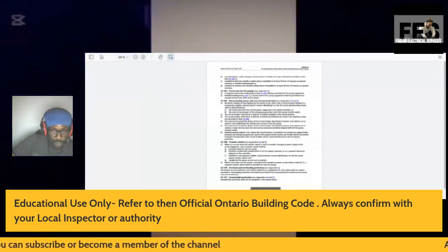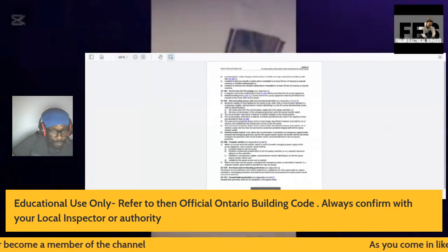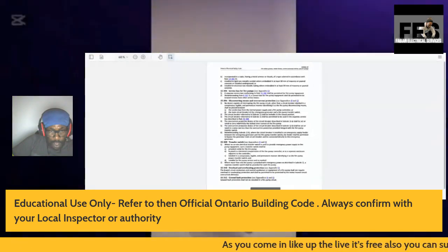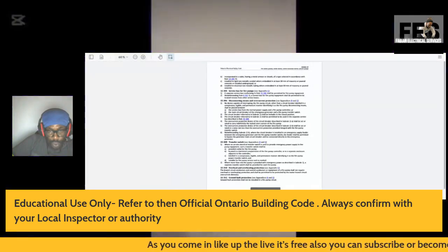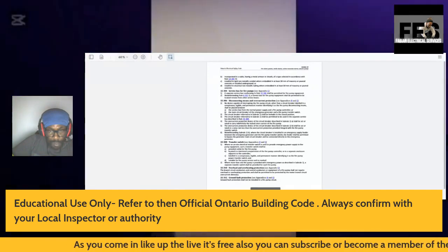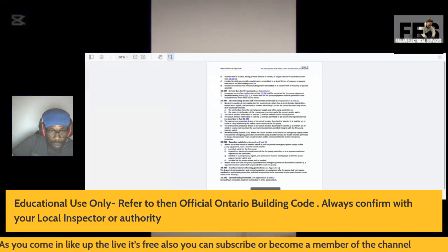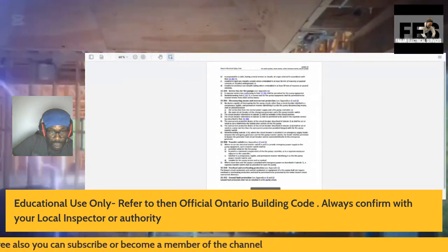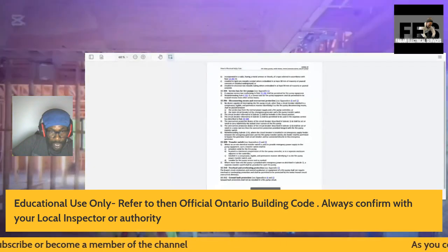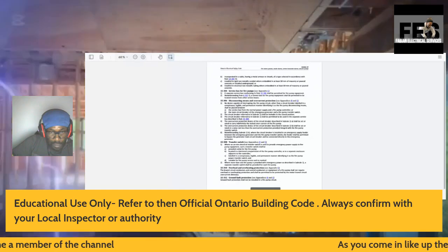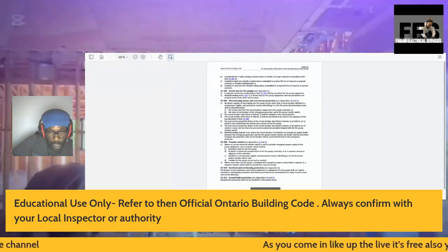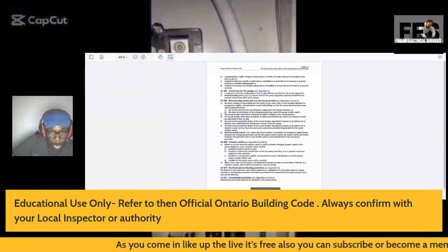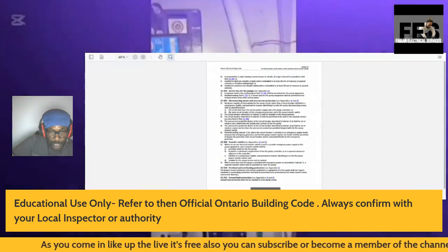It also has the transfer switch, and it tells you to see Appendix B and G. So I would refer to Appendix B and G, where an on-site electrical transfer switch is used to provide emergency power supply to fire pump equipment, such as the transfer switch shall be provided solely for the fire pumps, located in a barriered compartment of the fire pump controller or in a separate enclosure adjacent to the controller, labeled conspicuously.